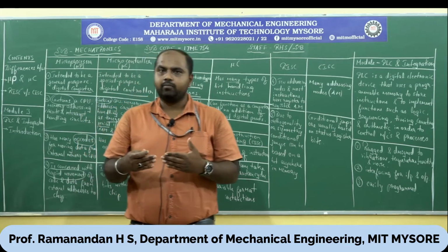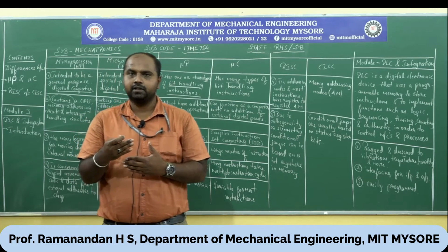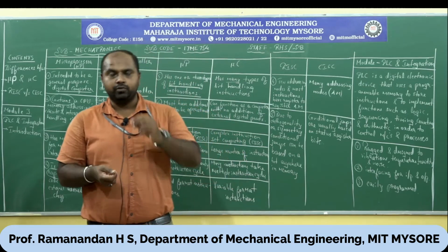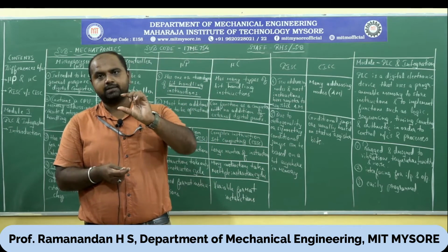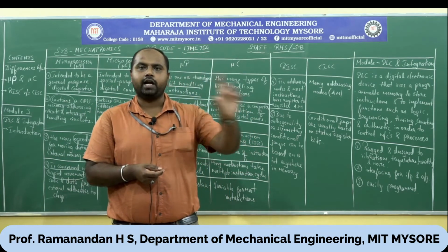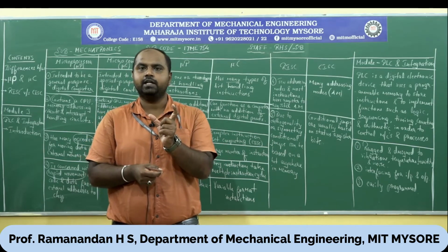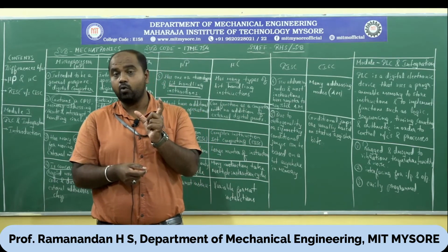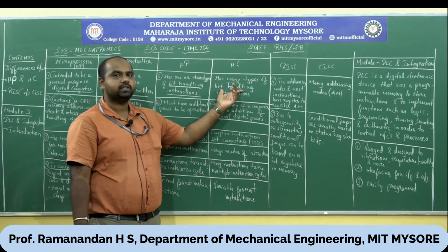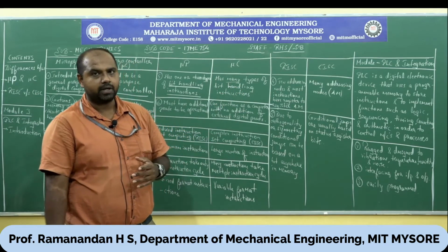Control system cannot take more time. It is a real time response machine. I repeat, it is a real time response machine. That means to say, within a short span of time, say milliseconds or just within a second, the action should take place. You have a very small amount of time for the response of a system or for the outcome of a system. So that makes a necessity for more bit handling instructions being incorporated in a microcontroller.